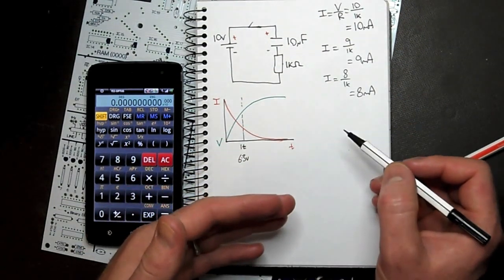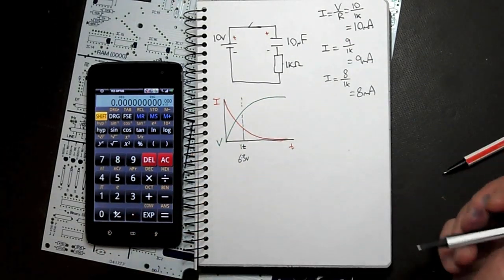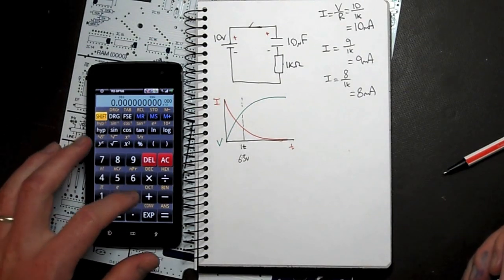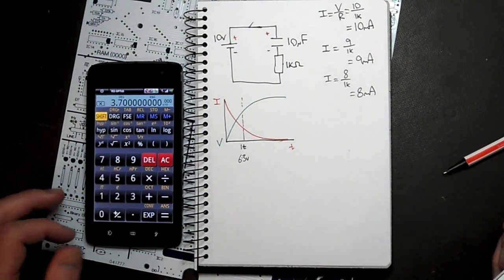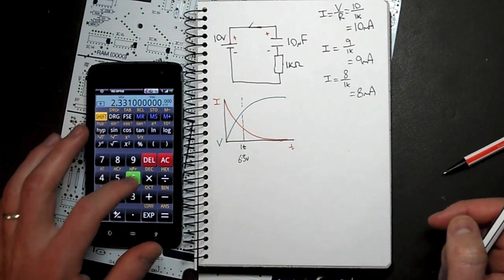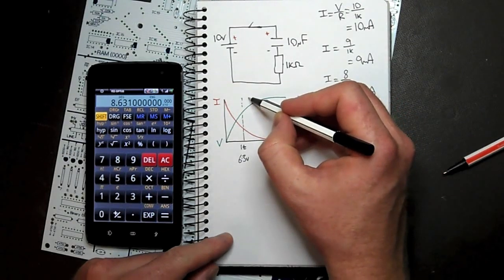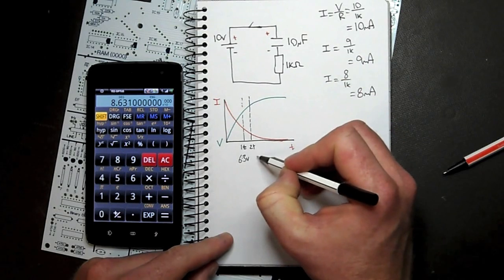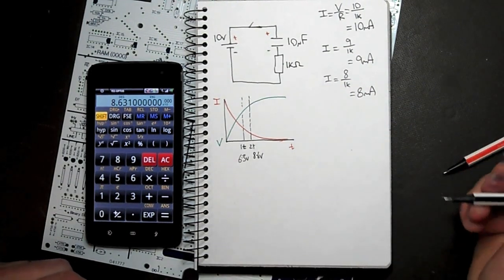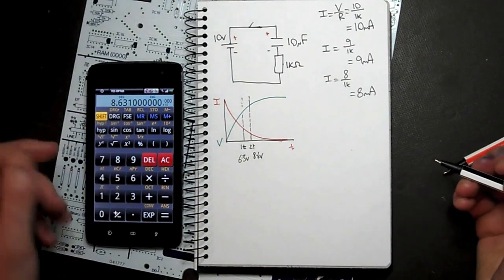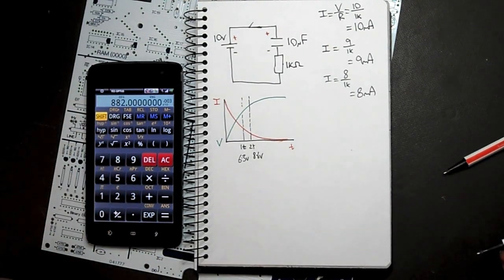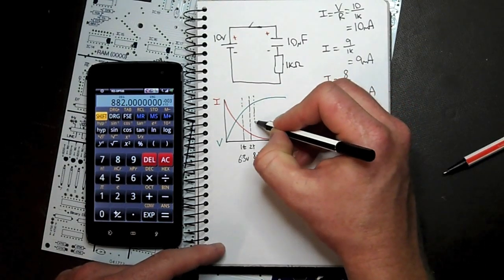Now after the second time constant, it will charge up a further 63% of what is remaining. So if there was 10 total, we already got to 6.3, then that leaves 3.7. So if we do 3.7 multiplied by 0.63, which is 63%, we get 2.3 volts. So we will now go up to 8.63 volts. So after our second time constant, we're about here, 8.6 volts. After the third time constant, we will go up by another 63% of what is remaining, which is going to be about 1.4 volts, 63%. We go up by not even a volt, so 882 millivolts. So after the third time constant, we only go up to about there.